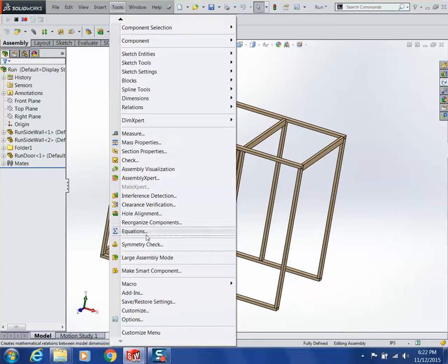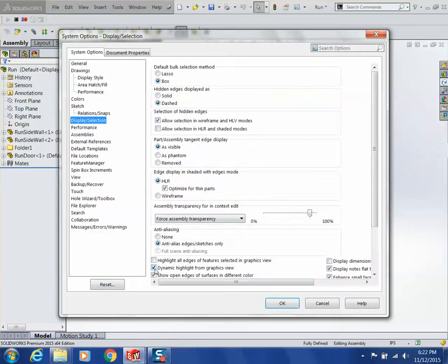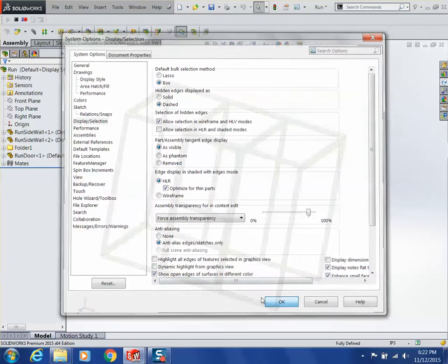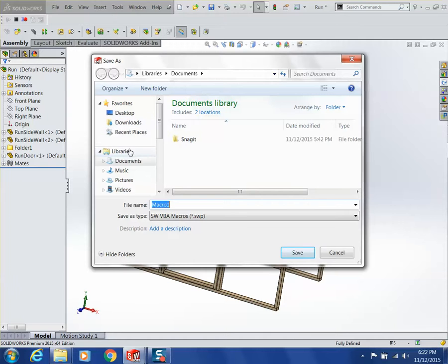So you can go to Tools, go to Options, go find the thing in question, do it, and then when you're done, hit Done. Gives you the option to save the macro. Then that macro does exactly what you just did. So if, for instance, I need that checkbox to always be on, I'd go make it be off, record a macro, turn it back on, save the macro, and every time you run that macro, it's going to want to turn that function back on for you. Saves you a little bit of running around.